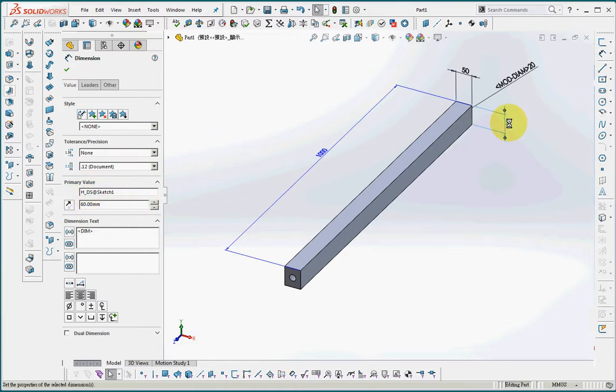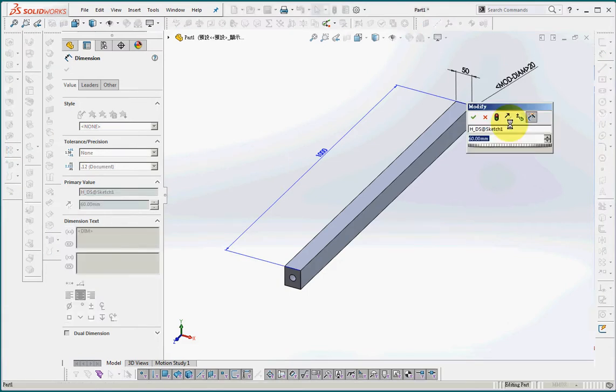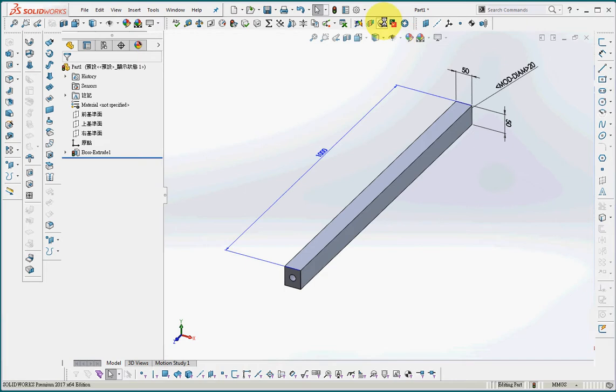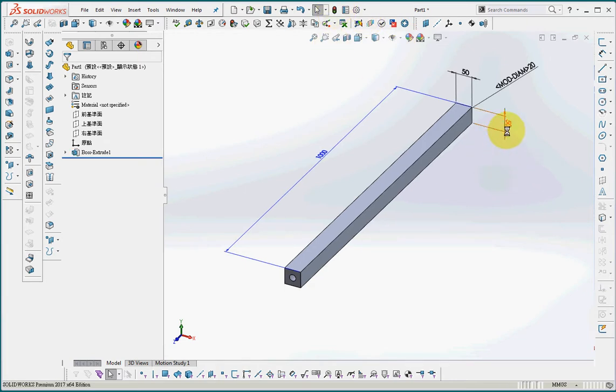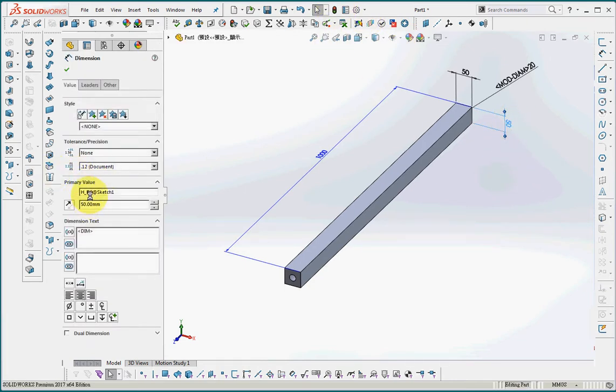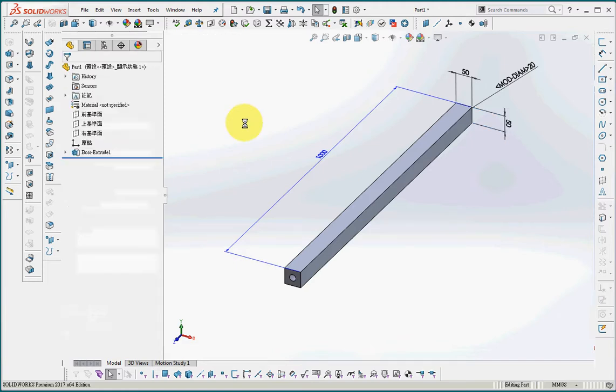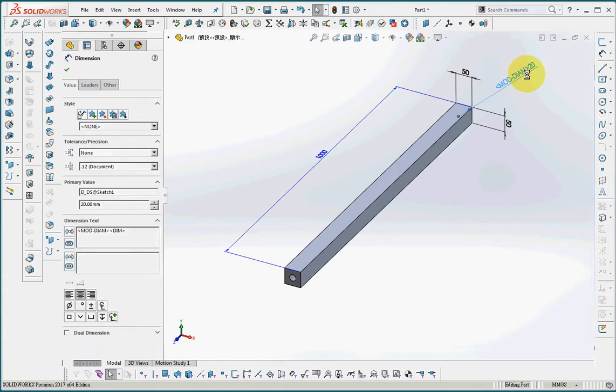And this is the height of the beam. The height of the beam will be 50. The height of the beam also has a ds key to transfer this dimension as a parameter to ANSYS, and the hole diameter is d, the 20 millimeter diameter.